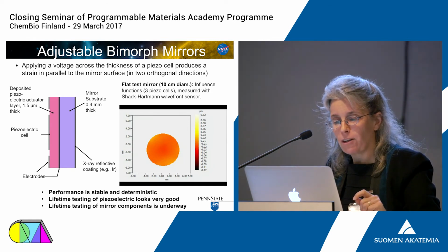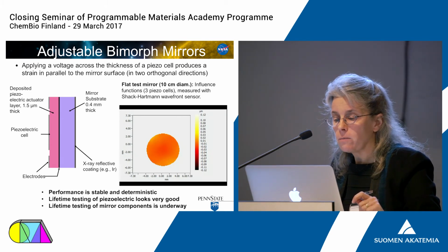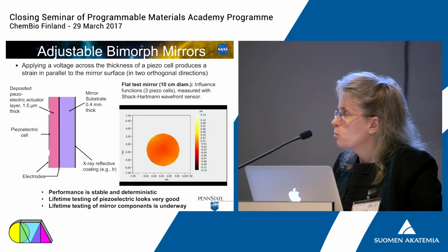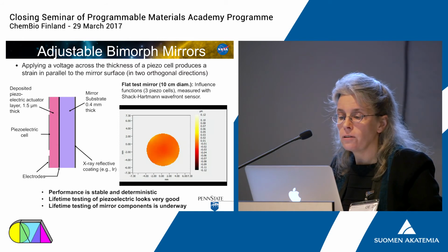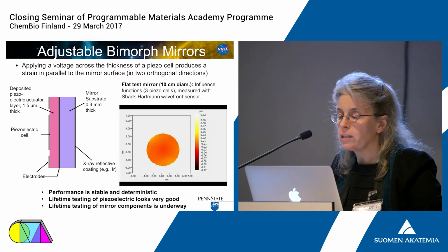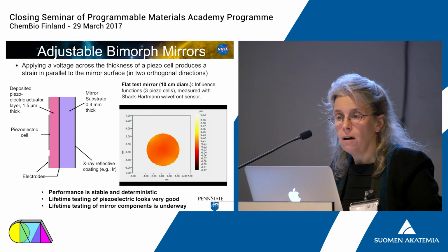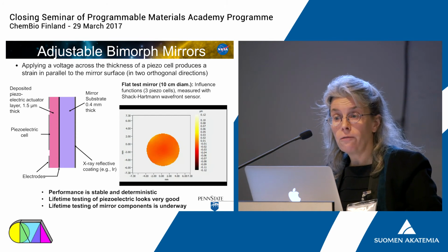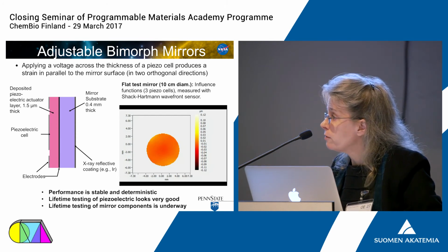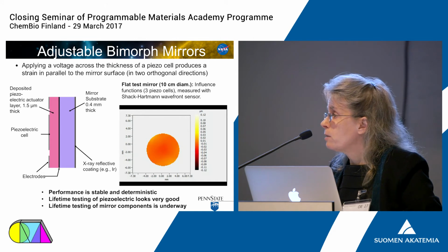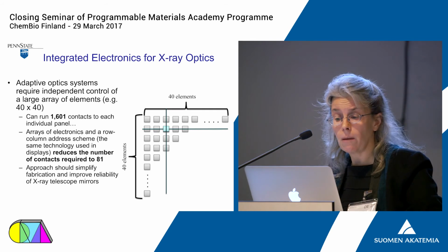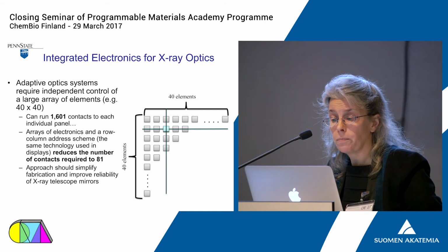So we're having a bit of a go at this, and so we learned how to do the deposition of these thin films on glass. What I'm showing here is actually wavefront measurements. So we're looking at the distortion of the glass surface that we can generate when we progressively actuate 3 elements on an adjustable optic. And you can see that we can reproducibly control the surface figure. The amount of deflection that can be generated is adequate to correct all of the projected errors in the optics for the next generation telescope.